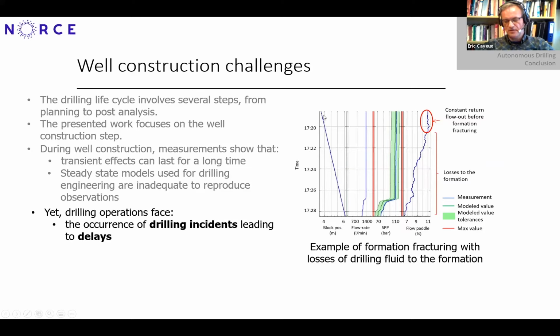Everything was very steady: flow rate, pump pressure. And the flow rate out was also very steady on the flow paddle. And then suddenly it started to decrease, indicating that we have fractured the formation and we are starting to lose mud to the formation. So these kinds of things need to be captured as quickly as possible and avoided if possible.